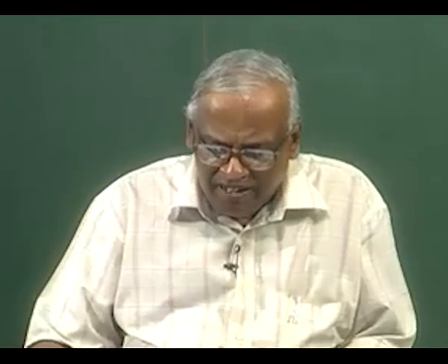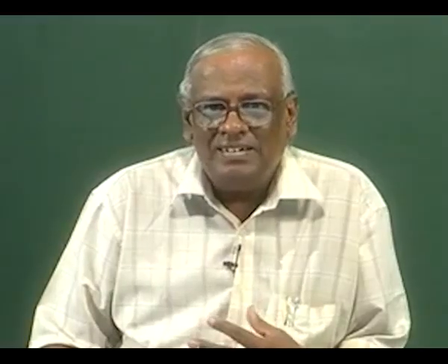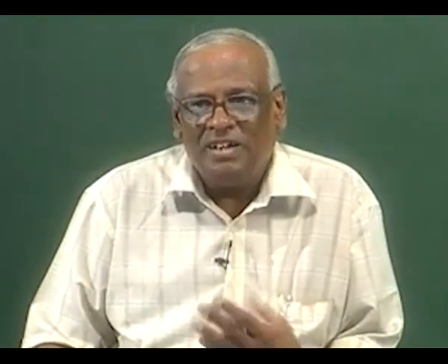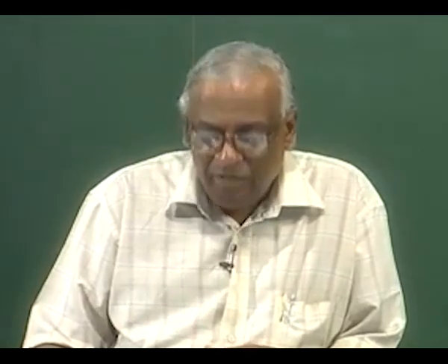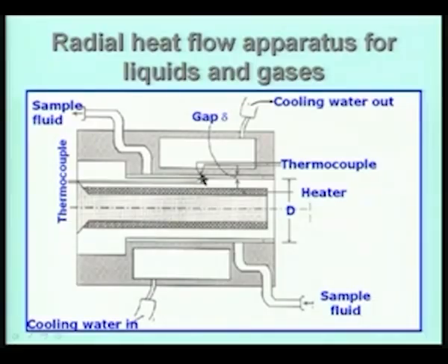So, the gap here is full of air, and the thermal conductivity of air has been measured by various people, and very accurate values are available from the literature. From the tables given in many books on heat transfer, you can find the thermal conductivity of air very accurately. So, all I have to do is give different amounts of heat into the heater, and find out the temperature difference across the gap. We also know the thermal conductivity of air at the mean temperature. So, you measure the mean temperature between the two, and we know the thermal conductivity of air at that temperature, and therefore I can find out how much heat is transferred from the inside to the outside by conduction through air.